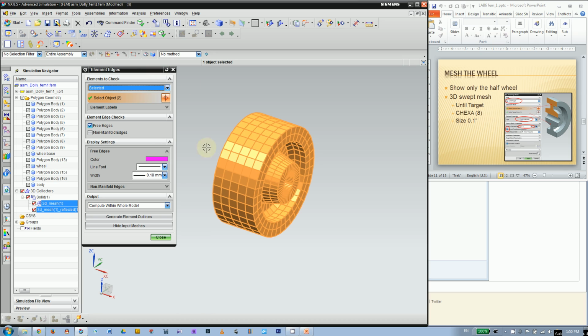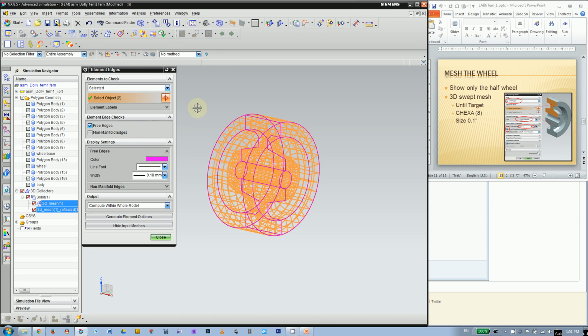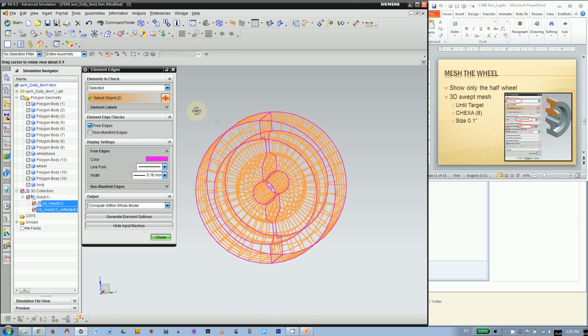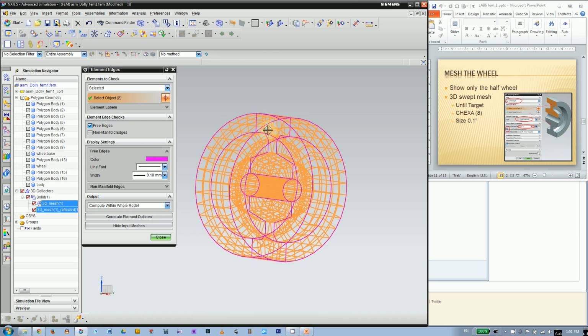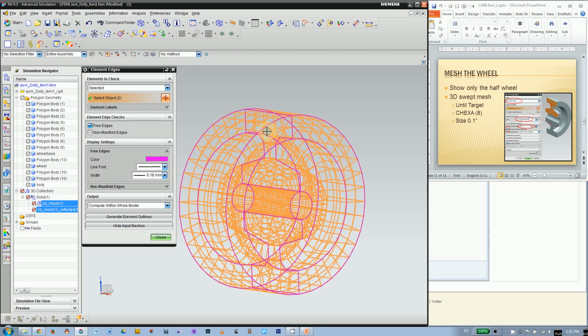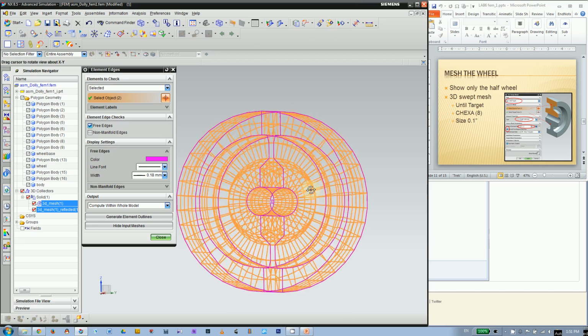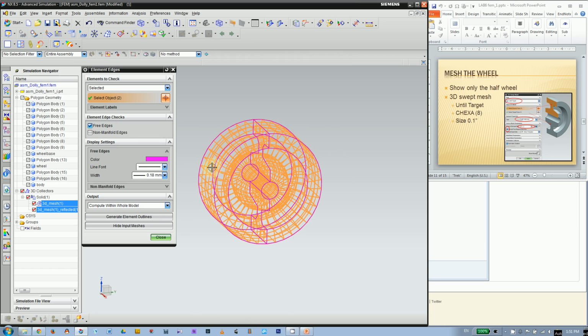Once you pick those two meshes, you can click Generate Element Outlines. Let me turn to a static wireframe. We have external edge inside the solid, that's the I-shaped cross section. The circles are good because they're on the outside of the solid, but you don't want any external edge inside your solid. That means you have a cut over there.